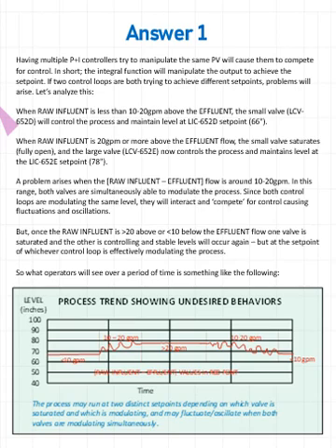So in this process, when the raw influent was less than about 10 to 20 gallons a minute above the effluent, the small valve, LCV 652D, will control the process. And it'll maintain level at the set point for LIC 652D, which is 66 inches.